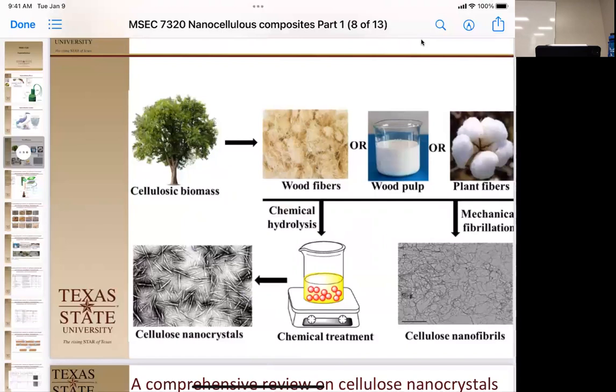If you took your cellulose nanofibrils and put them in an acid treatment, you would actually get that here. Okay, but most of the time when you do the fibrils, they actually want the longer persistence length. So they go through typically a mechanical processing step to get the fibers to be broken apart and out of little bundles. And so they have this much longer length to them.